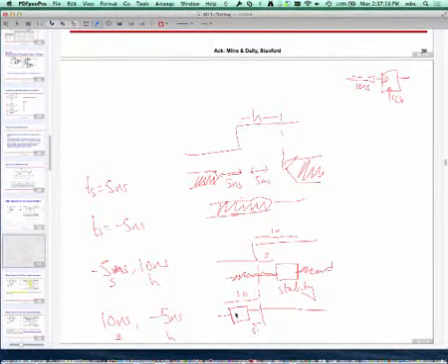What about when the hold time is negative? Then that is as if I have my ideal flip-flop and there's a delay on the clock line. The clock is getting delayed. Okay, that's all that's happening.